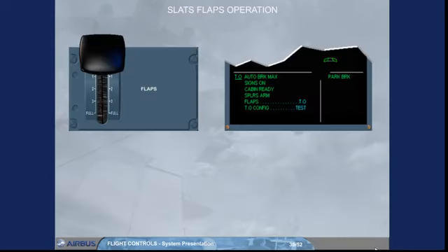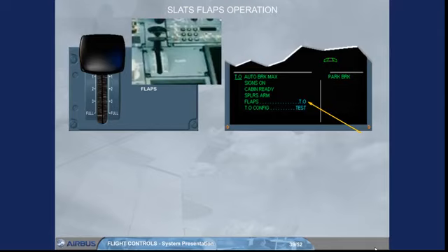The takeoff memo is normally displayed 2 minutes after the engine start and checked only during taxiing. For training purposes, we check it now. The flaps lever should be set to a takeoff position 1, 2, or 3. While the surfaces are moving, we will be looking at their indications on the engine warning display. To set the flaps lever to the related takeoff position, you need to lift up the lower part of the flaps lever, and then position it to the appropriate setting. Here, as an example, we will select the position 1.